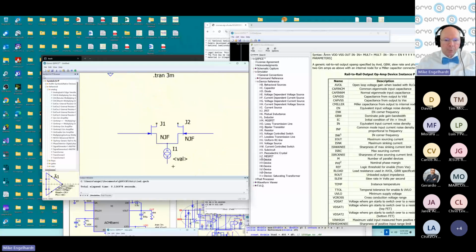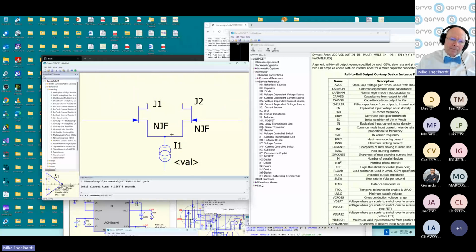All right, so this is what the input looks like to an op amp. A lot of JFET input op amps. A JFET input op amp has very little current noise that goes just from the JFET. But this current source often has noise. And since there's capacitance between the gate and the source, the tail current noise is conducted common mode out both inputs.